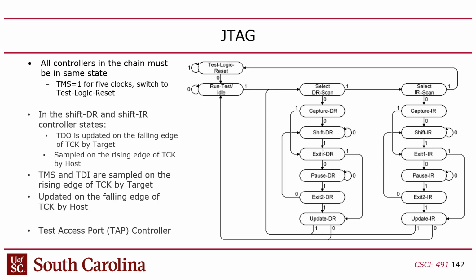So it would be really cool, I think, to have a bit-banged version of this. But I think it'd be a whole lot harder than the I2C bit-bang thing. But you could, in theory, bit-bang this or even design hardware for this, and then you can talk to virtually every chip, since pretty much every chip has a JTAG interface. It's like a back door, essentially, you can get in.